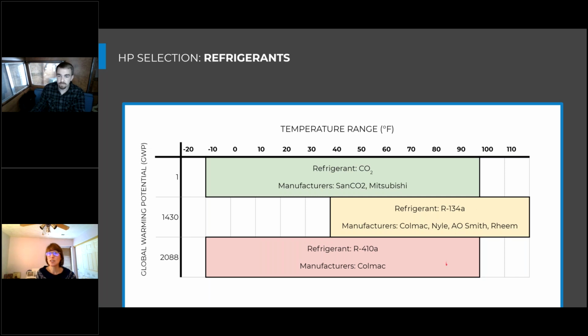Another question from Emily, which is a great one. For each of these types of refrigerants and products here listed, do we have a listing of the maximum water output temperature, or are we going to cover that later? I don't think we'll cover that specifically, the maximum leaving water temperature. In general, CO2 has a higher leaving water temperature across the entire temperature range, but that's something that is worth putting together on our end, so we should take a note of that for future content, as well as something that the manufacturer can really readily supply.